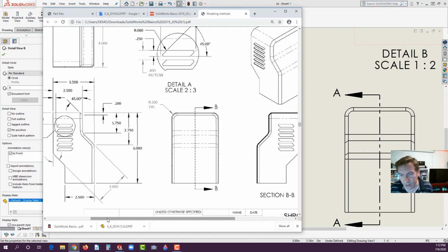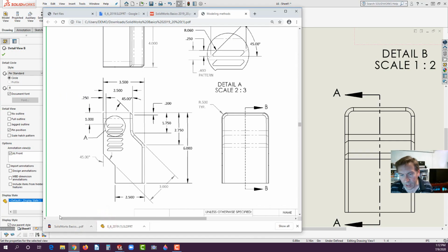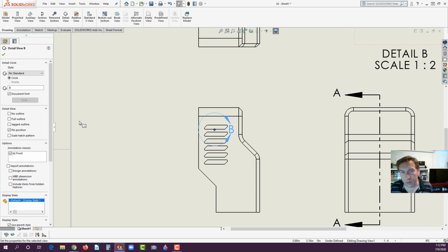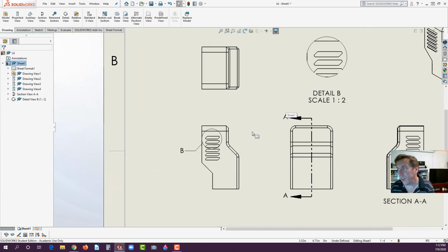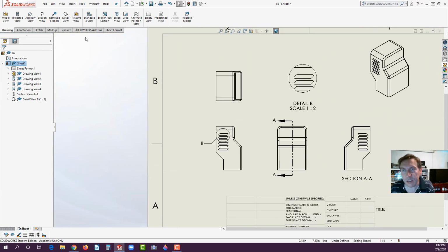This is actually a leader, A. So, actually it doesn't need to be A because I did the section view first, so don't worry about the lettering on there. Instead, select with leader. There we go. Okay, now we could start inserting the actual dimensions. Now don't worry about the scale that it doesn't match up with the other drawing. That drawing was done in an older template that had more space. Even though it's the same size, the actual border wasn't quite as tight.